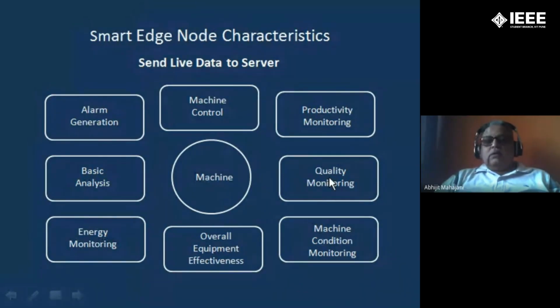In manufacturing, the parameters are so vast that it is not possible to write a program and get a correct output for quality, because even the atmospheric temperature can play havoc many times. So your quality must be monitored, and what we suggest is you have an inspection stage between every two production machines, and if something goes wrong, you just stop the line there to avoid rejection.